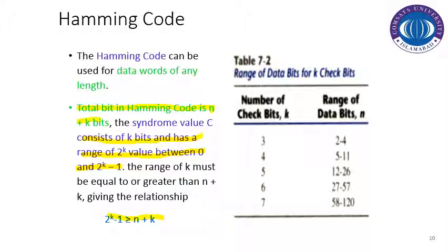if the check bits result in all 0, it means that we don't have any sort of error, and it results in 0 in that particular case if we are using even parity. If the check bits have some number, that specifies the specific placement which contains the error bit.